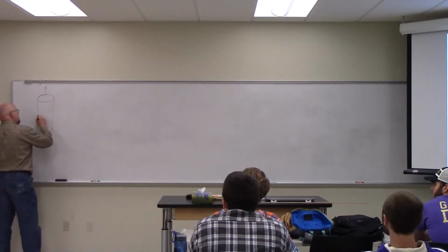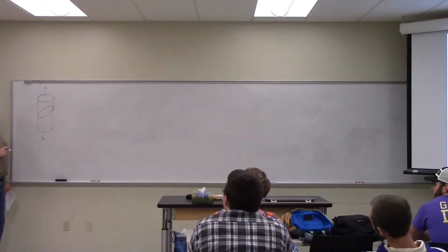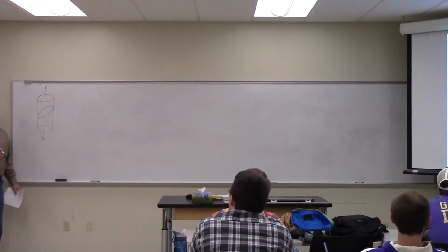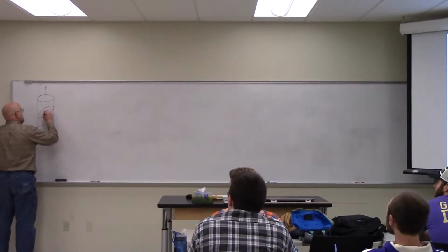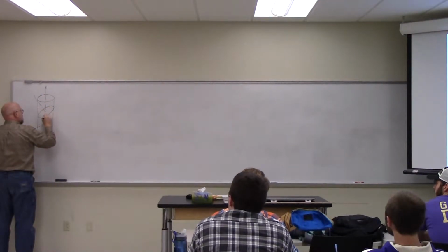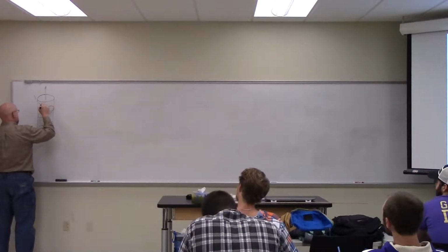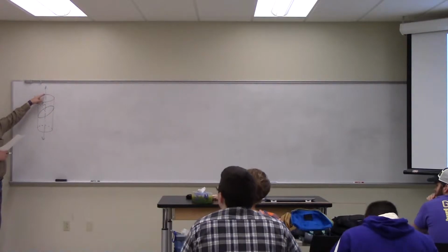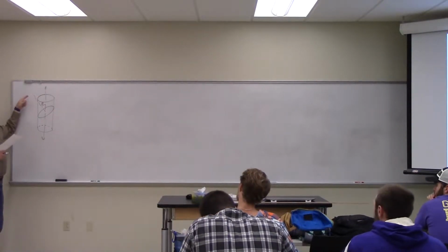So there's going to be some plane through here on which that slip is going to occur. This is one of those 111 planes. That make sense? So that plane has a normal, and there's an angle between the plane normal and the pulling direction. I'll call it phi, or theta, I don't know. That's the angle between the pulling direction and the normal to the plane.